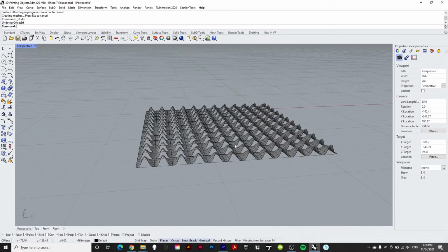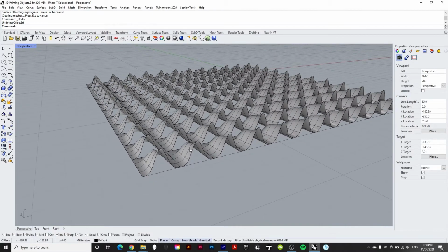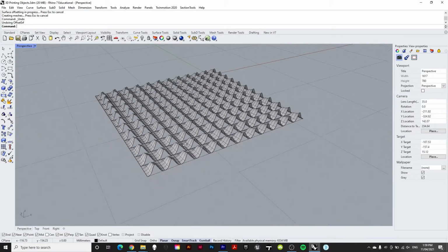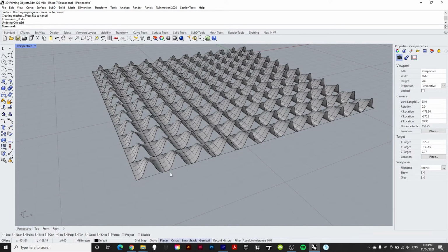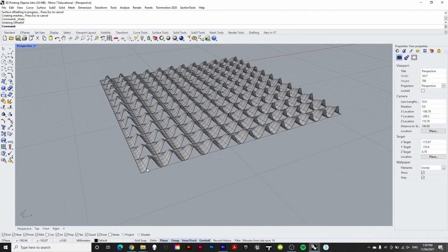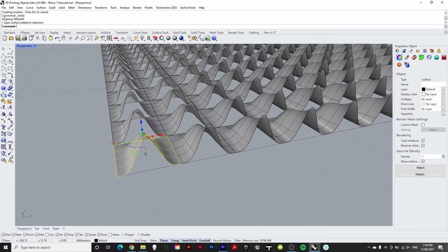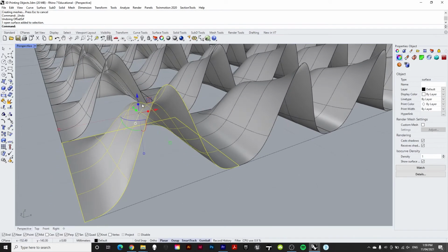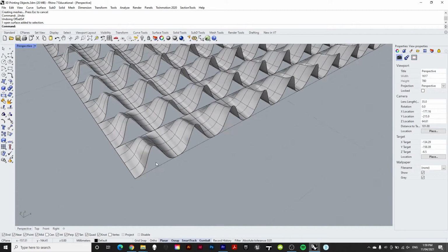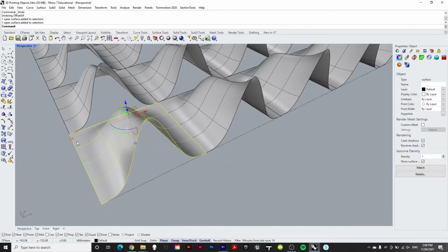So we can see we have an arrayed surface here, which is made up of a bunch of these smaller little surfaces, and together they're going to make a complex geometry which is quite tactile and haptic, something really interesting. First problem we noticed before going to our 3D printer is that these are made of individual open surfaces, so the 3D printer is not going to be able to read any of this. Remember, in Rhino these are infinitely thin, so they don't even have a geometry to them while they're still surfaces. So I would be making these into solids straight away.